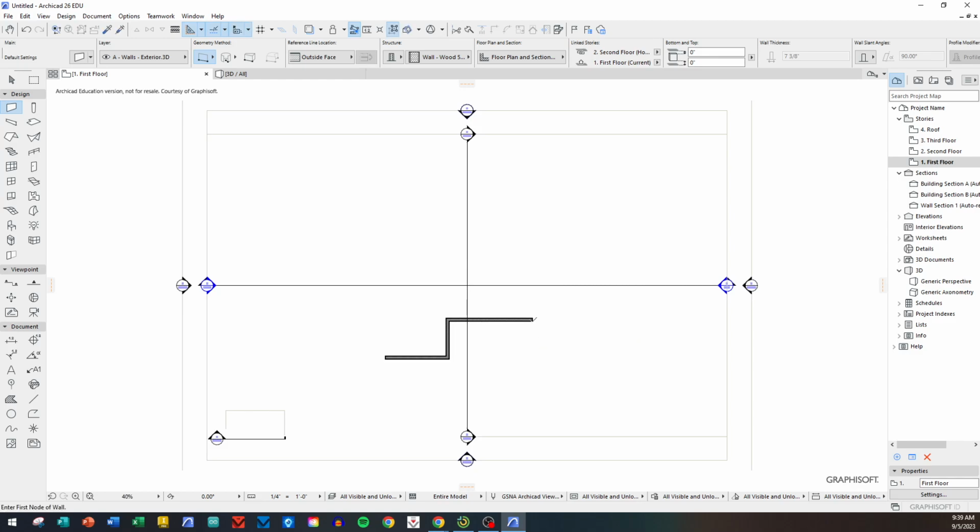Now, if you watch my cursor, notice the dark side is the outside of my building. That's the side I'm keeping to the outside. If I mess this up, it's going to flip around that draw side, and I'm going to end up having to mess with some of my dimensions later. So just be attentive to that. Now this goes back 32 feet, it comes straight across.